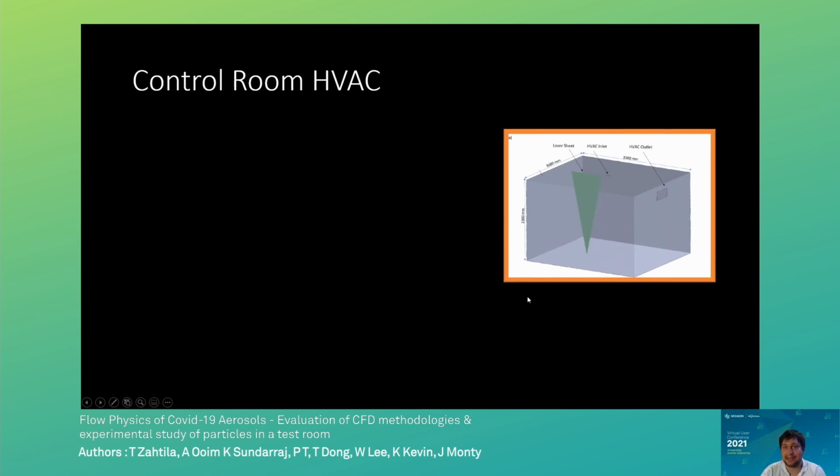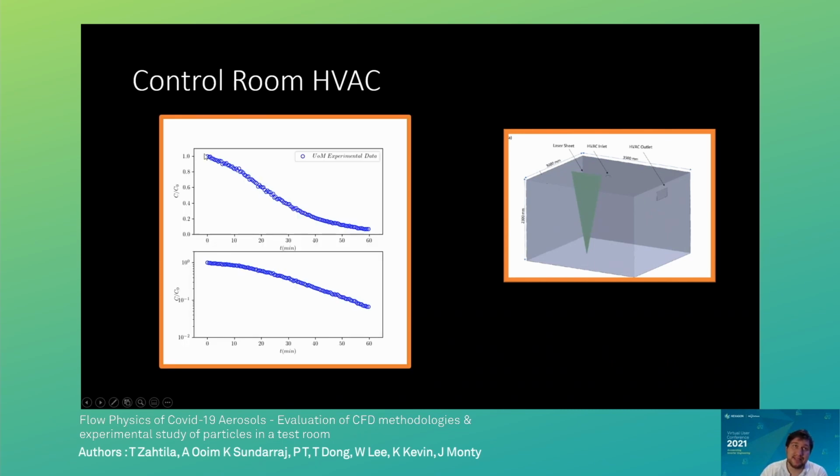But taking a step back, that was some work we did that was published for the medical community because they're interested in hospital rooms. But taking a step back, we removed the air cleaner, and we were just interested in using our laser sheet to see how many particles remained with time. So you see the University of Melbourne experimental data. We then simulated that room using MSc Cradle software, where we got what I will call a pretty good agreement.